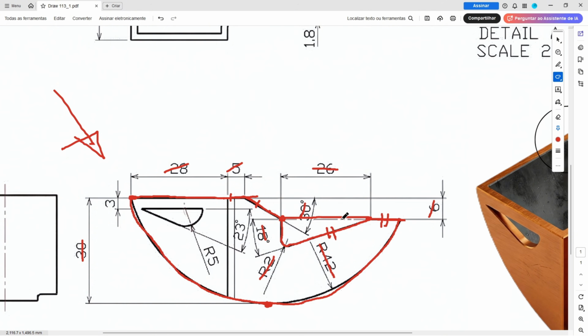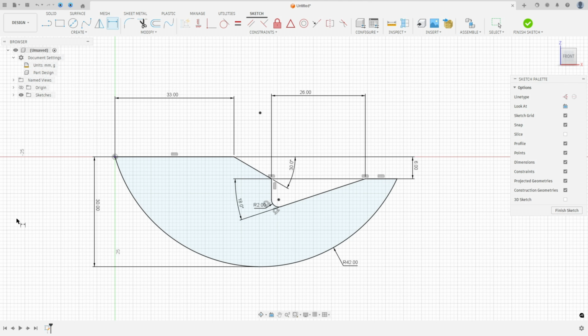And here we will divide this sketch in two. So we will create this line here. This line is coincident with this arc and coincident with this line. And the distance between this line and the midpoint is 28 millimeters. So select line, make a line here. Go to sketch dimension. The distance here, 28 millimeters. And press OK.